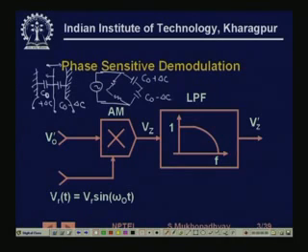Okay. So, what happens is that now we see that the output becomes modulated. If you take a bridge and take the signals from here, what shall we see here? Obviously, this excitation is generally of high frequency, typically of the order of, let us say, 2 to 5 kilohertz or even sometimes a little more.